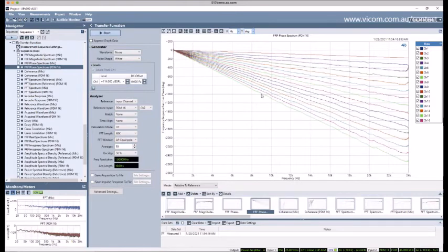And so now we see something very close to the ideal response. And you notice here I've set the reference microphone to be the number 2 microphone in the PDM array, which thanks to our little swizzling, we actually know is the number 1 microphone. And here we get a classic view of that phase delay from each of the microphones that's a little bit further away from the sound source than the reference microphone.